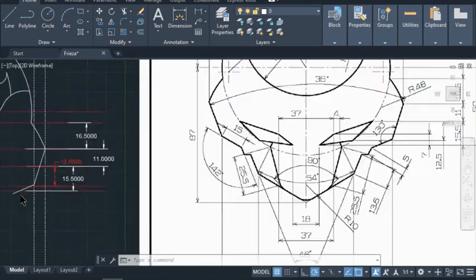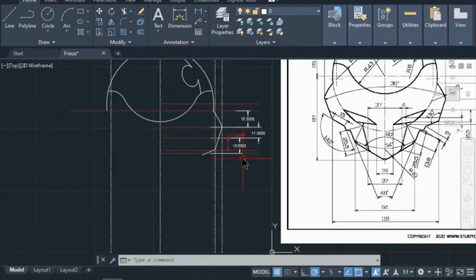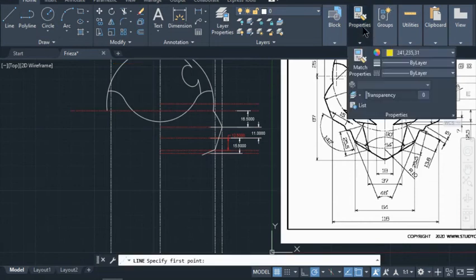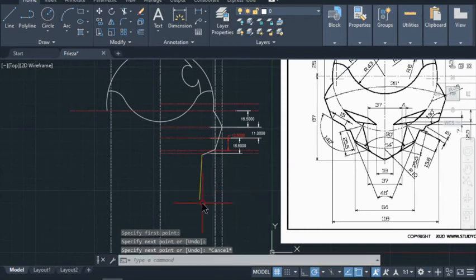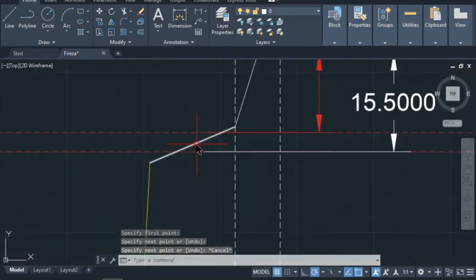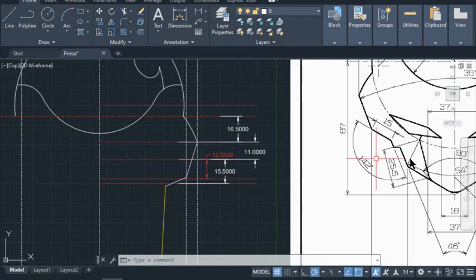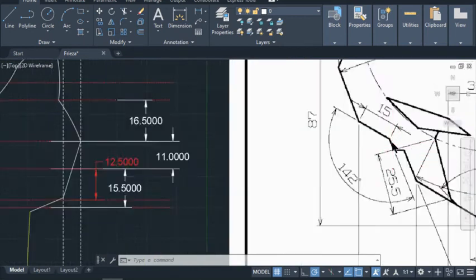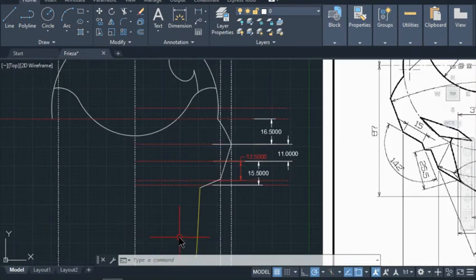So we're going to go ahead and look at that. So the rotation is 142. So let me draw this in for you guys to look at first. It's yellow. That's good. So this is the angle that they're talking about. So if I draw something here, this angle from the white one to the yellow one, that is 142. That's the angle that they need. All right. And the length of the segment was 5. This short segment here where my crosshair is right there. So let me go ahead and delete this right here.